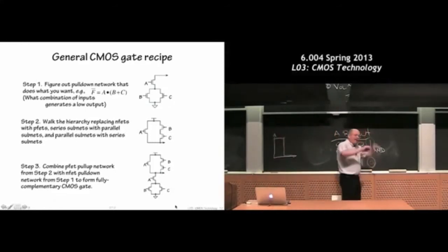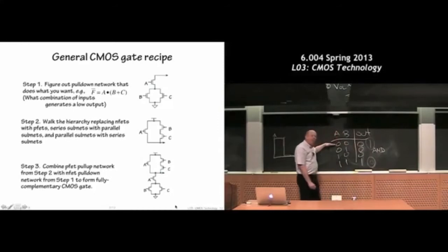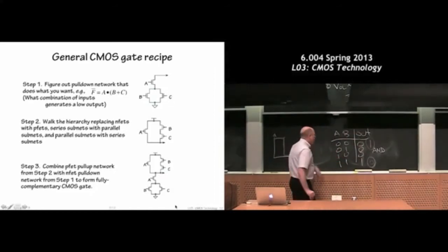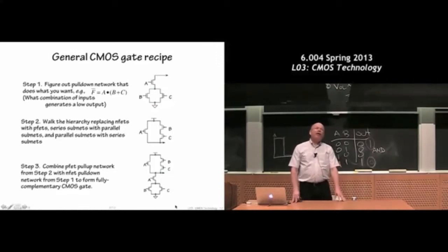It doesn't matter what network you've designed, okay? So, can you implement this in a single CMOS gate? No, you can't. There's just something about this truth table. So we can't build a single CMOS gate for every possible truth table. We can only build it for certain types of truth tables, the ones that describe inverting logic. Logic where rising inputs lead to falling outputs.